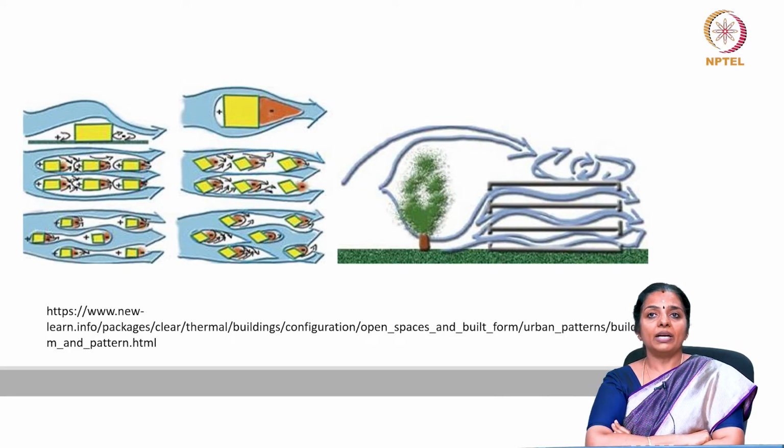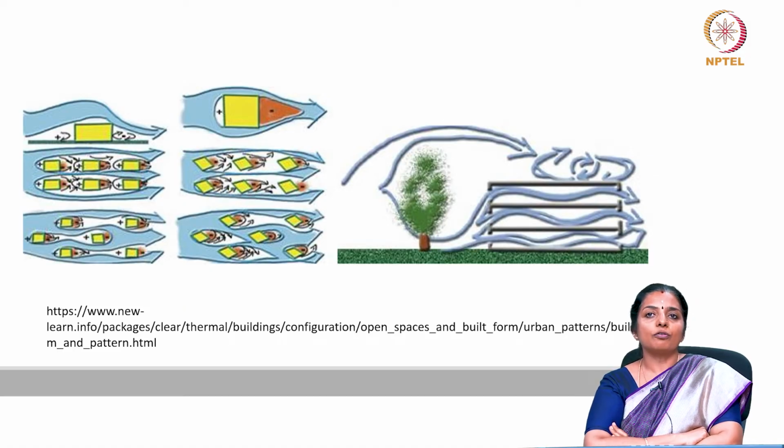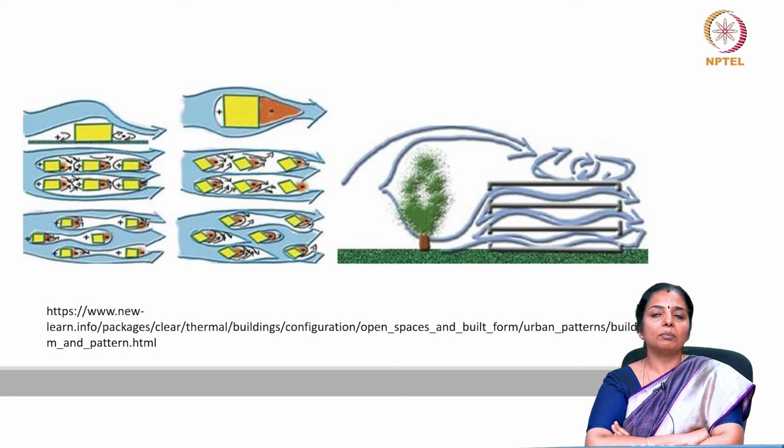When large built volumes, or say a long row of buildings, are placed perpendicular to the wind direction, then shielded zones are established between the buildings where wind speed might be just a small fraction of the speed above the building's roof, or in streets parallel to the wind direction. In this case, the distance between the buildings has little effect on the speed of currents between the buildings.